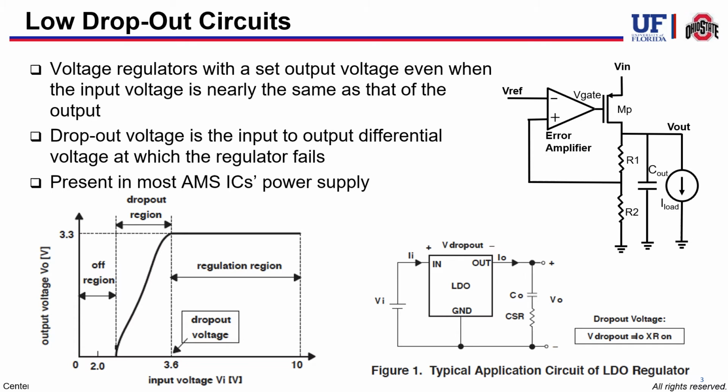Some important components to keep in mind in the basic architecture of an LDO are an error amplifier with a high open loop gain, a constant DC reference voltage, the output voltage, which is determined by the values of this reference voltage and by the R1 and R2 resistors that can be seen in this image, a MOSFET acting as a pass transistor to achieve regulation by controlling negative feedback, and finally, the capacitor at the output, whose value will be determined based on the load current.